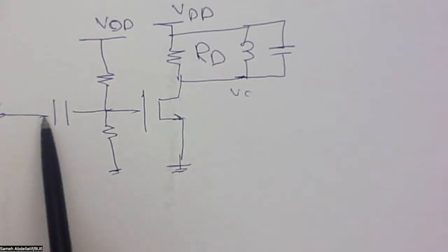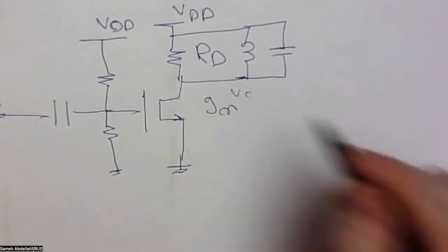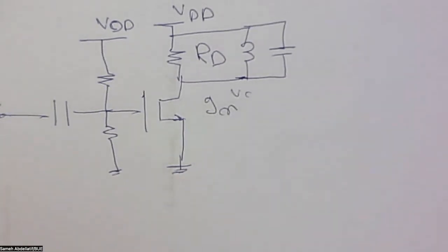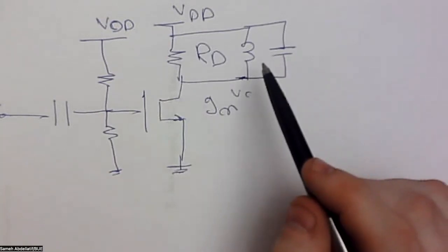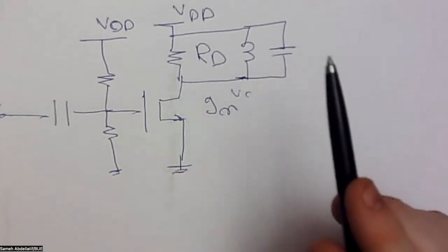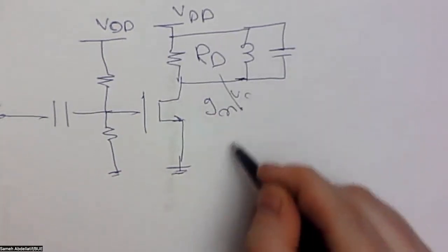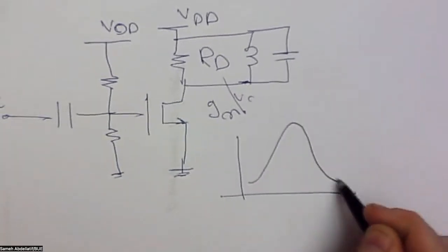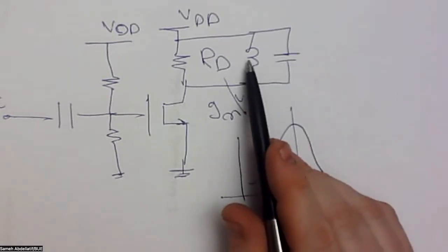First, this gate-drain relationship, in terms of, if you remember gm, the transconductance of a MOSFET, will enable you to perform some sort of a gain for your signal. But this gain will be only considered for this filtered signal. Here we have what we can call a resonance effect. Typically, the meaning of a resonance effect is a certain frequency at which the impact of the capacitance is cancelled by the impact of the inductance.